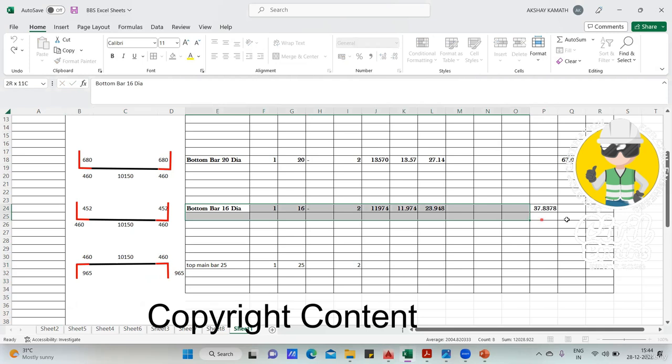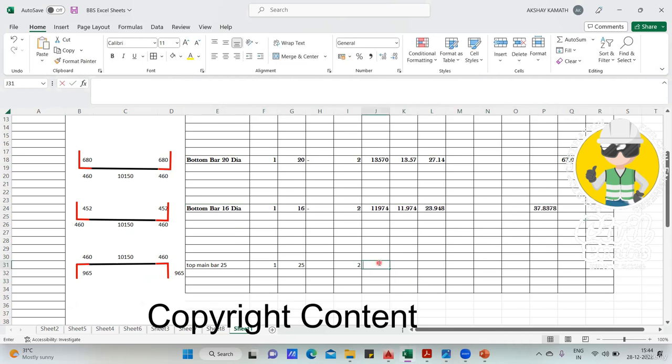Otherwise, you could have copied the same thing and pasted. That also you could have done, but I didn't do. Okay, now you add 965 plus 460 plus 10,050 plus 460 plus 965. So this answer is almost 13,000. That is 13 meter, which is greater than 12 meter. So I need to add one lap length. So plus, open the bracket, 57 times the diameter. You take the diameter from here and close the bracket, enter, finish. So now this is your total cutting length.